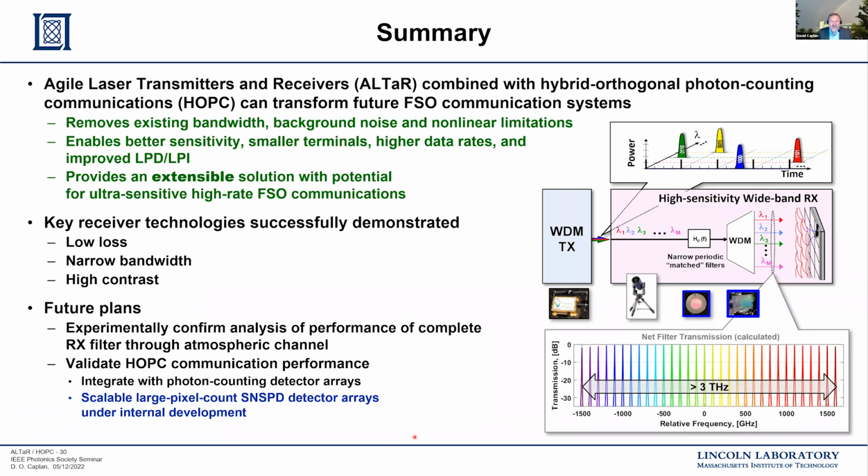In terms of scaling the power efficiency or the size, weight, and power of the filters, there are designs that we have that I haven't gone into yet. The etalon-based approach can work pretty well. It does need to be temperature controlled, and we have some ideas on that. I know that there are some companies that have implemented small form factor etalons that are of interest, that are fiber coupled. In this particular application, we're really enjoying the fact that our optics was free space, so we could accommodate the multi-spatial modes that would operate efficiently for transmission through the free space optical channel.